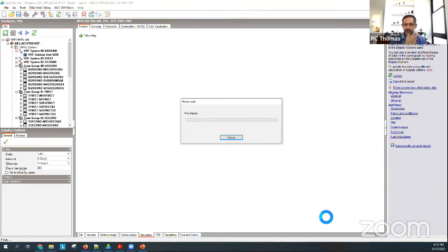So what is the model doing? First, every hour it's working out the amount of energy it needs to bring that space to the comfort condition that you specify. In this case, I specified a thermostat of 23.9 for cooling. So it works out how much heat it needs to extract from each space to get there. Then it works out how much energy the fan needs to put in, how much energy the compressor needs, and so on to deliver that cooling.